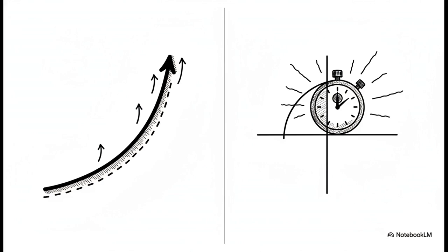Okay, it's really essential we don't get our wires crossed here. In these specific, non-S-shape integrator models, K is no longer a final steady state gain, simply because there is no steady state. K is now the velocity gain. It's literally just the slope of the runaway incline. T, meanwhile, remains our time constant, which is a measure of the system's dynamic lag, and we mathematically pull that right from that L plus T intersection point we just found.